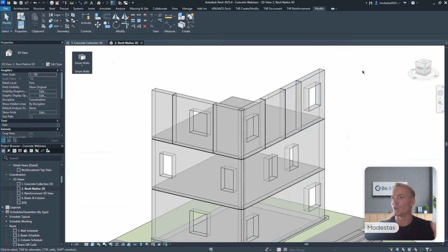So it requires me to put in additional effort to create additional views. That view should contain some reference planes with some offsets to find the exact locations where the split should happen. So it requires additional effort and additional stress to split those walls in the precise locations with precise distances.